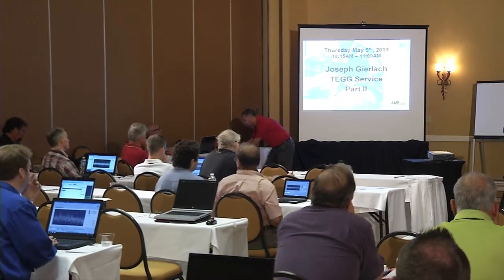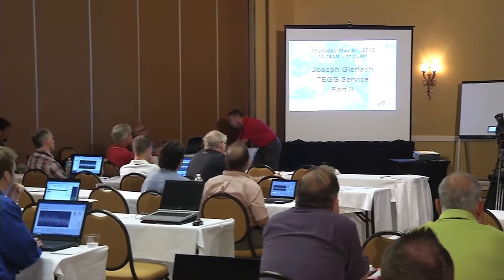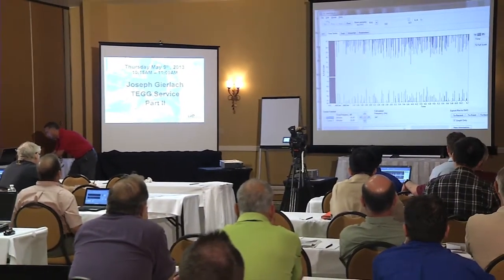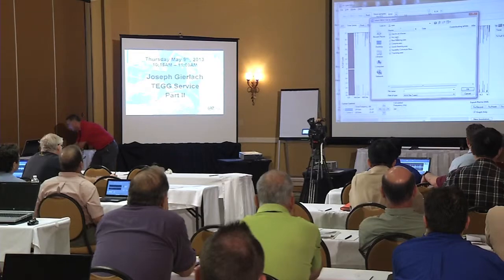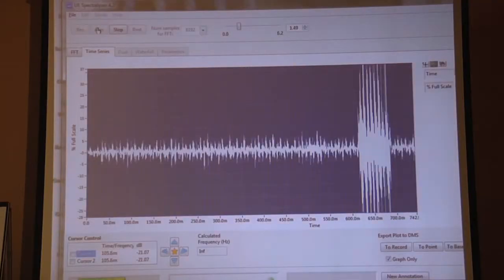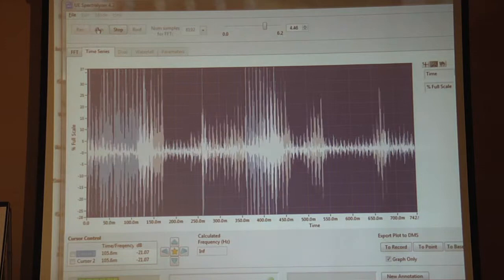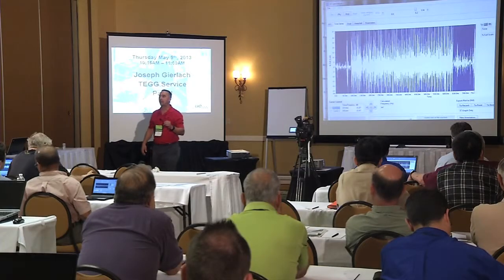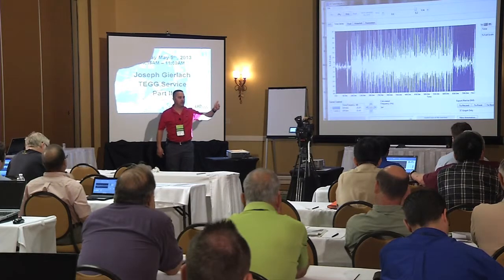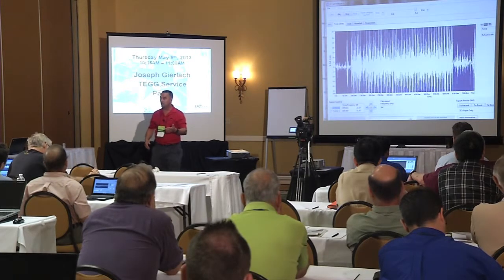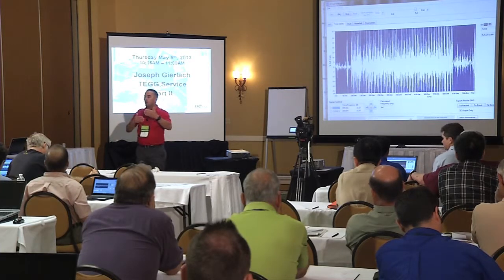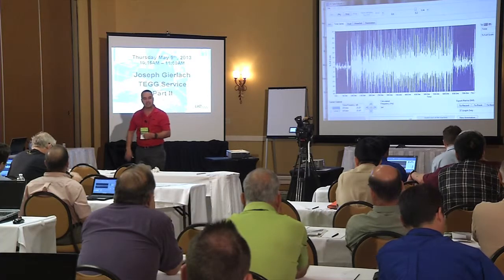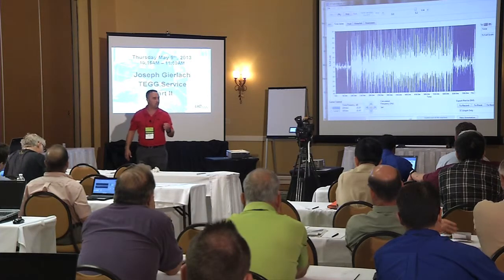Now, the other one we were talking about was arcing. And again, this is, we know, where it's failing. So we looked at the FFT earlier, and everybody agreed that the FFT for arcing and tracking were similar, right? Both recordings in the FFT for arcing and tracking had what? Some 60 hertz peaks and a lot of frequency noise. One could not distinguish the difference between which wave file was which by using just the FFT analyzer, was the point I was alluding to.